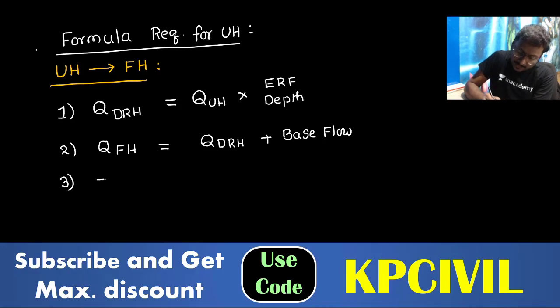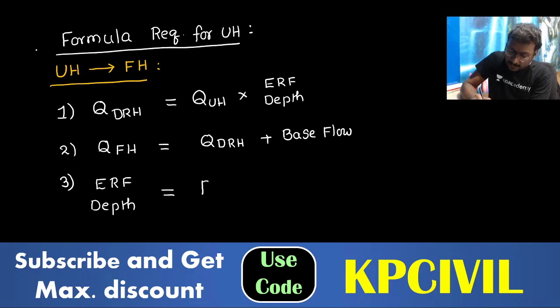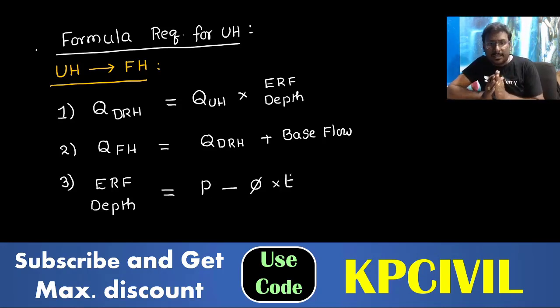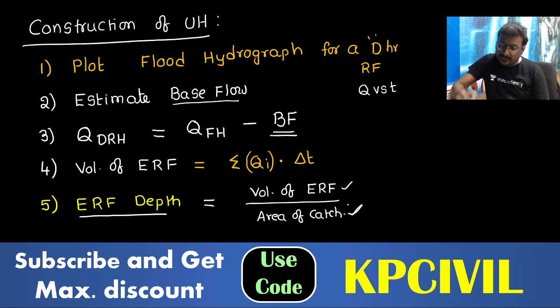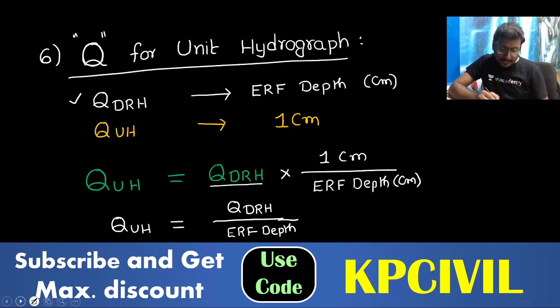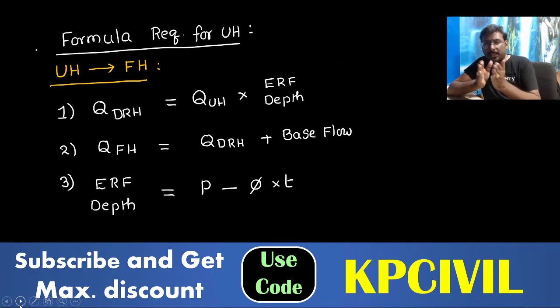How will you get effective rainfall depth? Very important, from infiltration data. From infiltration data you will get effective rainfall depth equal to precipitation minus phi into T. That is considered effective rainfall depth. Or you may take the previous formula also: volume of effective rainfall by area of catchment. You may use this formula, or you may consider losses: precipitation minus phi into T gives effective rainfall depth.